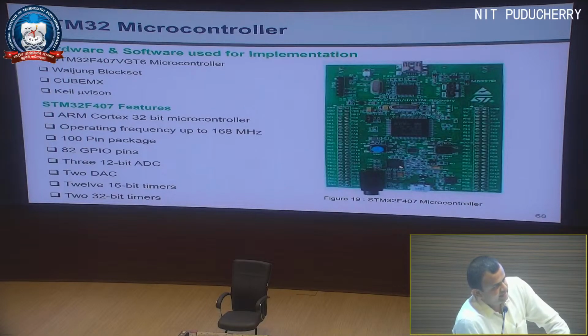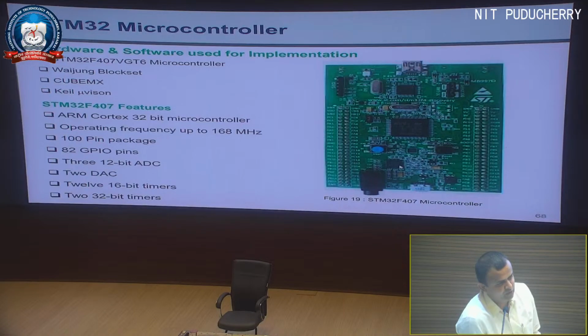Yes, that is what we are trying. We are trying to keep the motor in the hub, directly connected to the wheel. But again, even there BLDC is leading over the SRM. As far as my knowledge goes, I don't know of any electric vehicle fitted with SRM. I am doubtful. It is still in the research stage only.